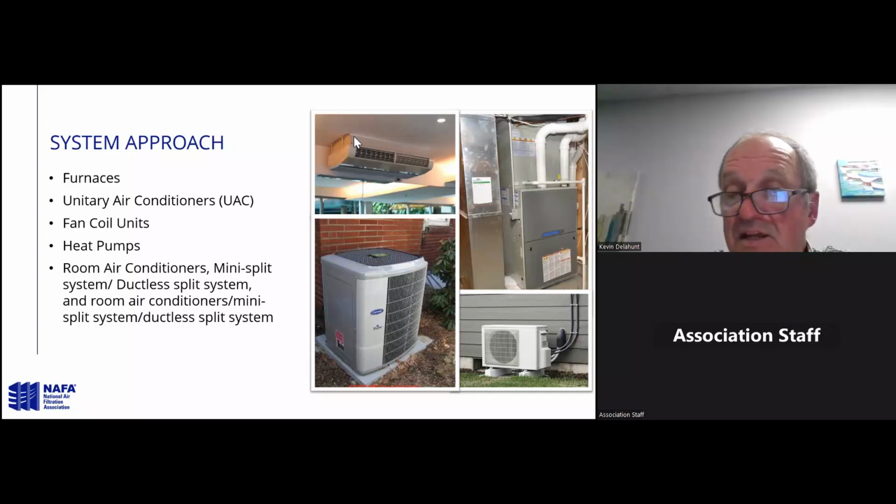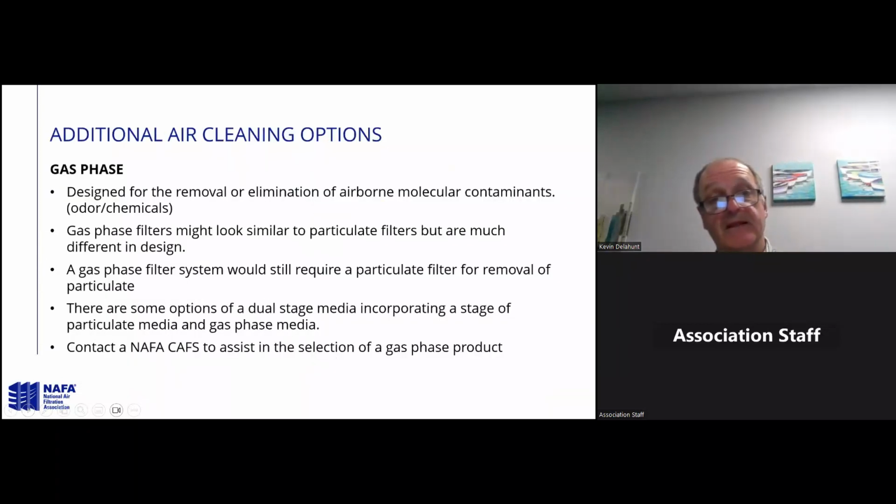So in all of these, we recommend a MERV 11 filter. In most of them right now, it's very difficult to even get a MERV 11 filter into what we're given as the filter apparatus or the hardware. We don't really have a lot of physical room to do that. Going forward, there's no reason why it can't be added. But right now, it's hard to retrofit these systems from maybe a MERV 6 to a MERV 8.